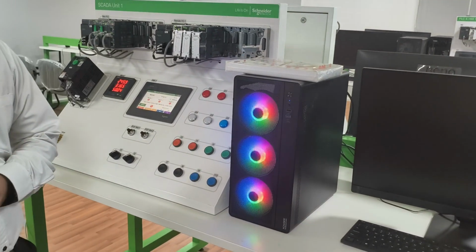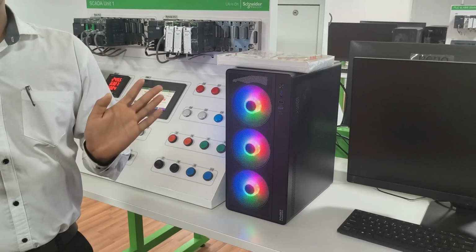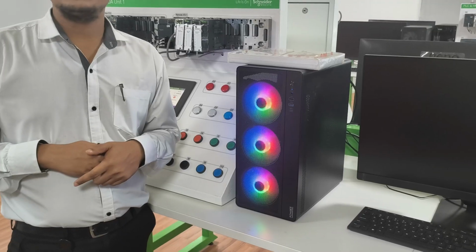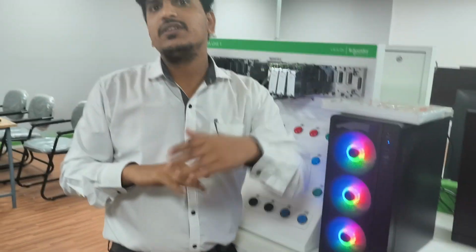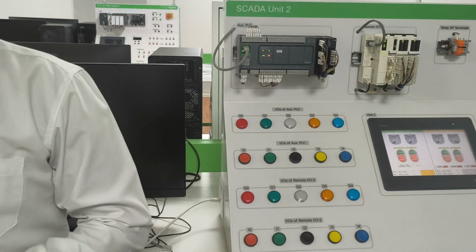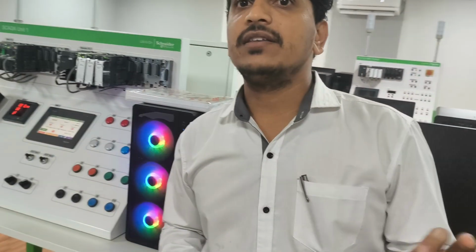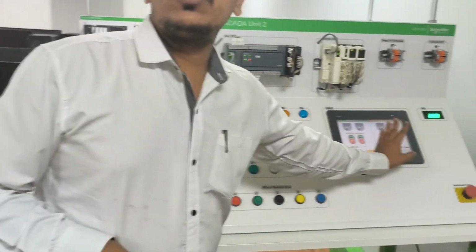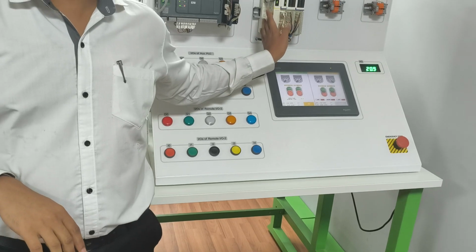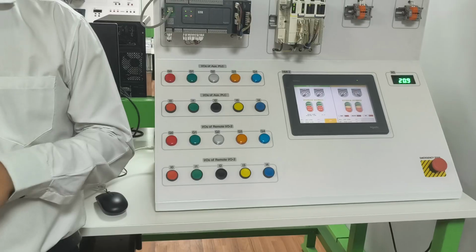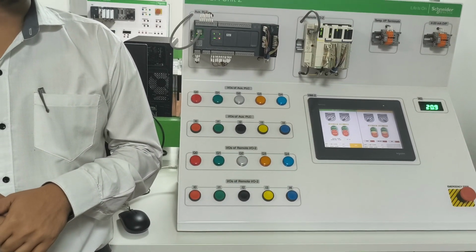Water will be pumped to the tank, and then it will be stored in the reservoir. From the reservoir we need to purify the water. For purification, again we'll pump the water to a different place. There, to purify that water, again we need some pump, valve, and processes like purification, chemical dosing pump. So for that we are using this PLC, remote IO to PLC. It will process all the water, like it will clean. Chemical dosing pump, CDS, we call it.